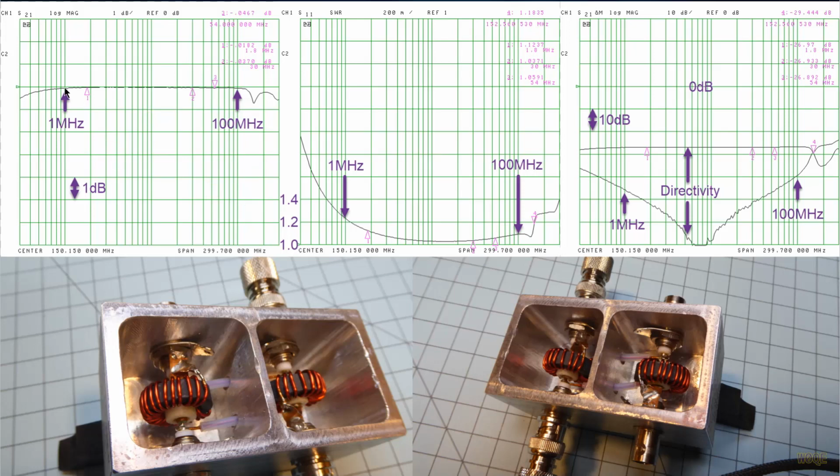If you measure the circuit's through gain, so that's taking the input and output port, and it's symmetrical on both sides, we see the gain from 1 megahertz to 100 megahertz goes from, I don't know, at 1.8 megahertz it's 0.02 dB down, and at 50 megahertz it's 0.05 dB down. I mean, it's incredibly flat. If we look at the SWR of the through circuit, we see pretty much what we saw before on the graph. SWR runs from about 1.